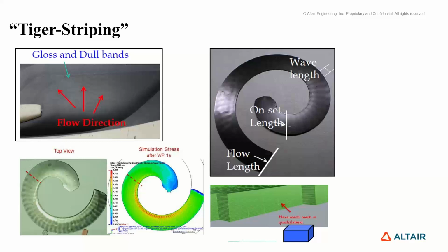It builds up pressure until it stops the flow front. What's coming in from behind still keeps coming in, but it halts the flow front and starts to compress the material behind it until the air can dissipate and get out, like the eddy current. It dissipates, and then the flow front can start picking up again until it builds up pressure and stops the flow front again. And so you get that same kind of oscillating, dithering effect.